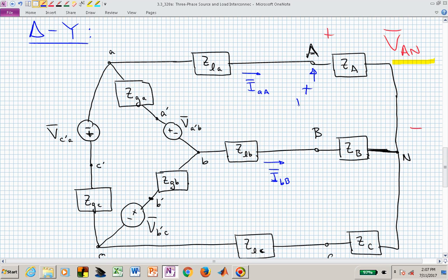It's now this voltage from the terminal A to the terminal B, and that now has to, by KVL, be algebraically combined with V sub BN and V sub AN to produce the A phase line to line voltage, or the line voltage at the terminals of the load, and that's in contrast to the A phase or the B phase load voltage in that configuration.